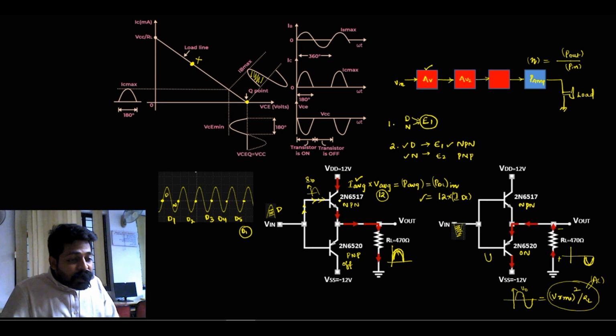So there is a first transistor and after that a second transistor, both will be active and taking power, this one from this one and this one from this one. Now the total power is what they will be taking from the VDD, around minus 12 times the IDC current, because the current is going over there, so I keep it as a minus notation. Minus of minus becomes a plus, so 12 times IDC I have to calculate.